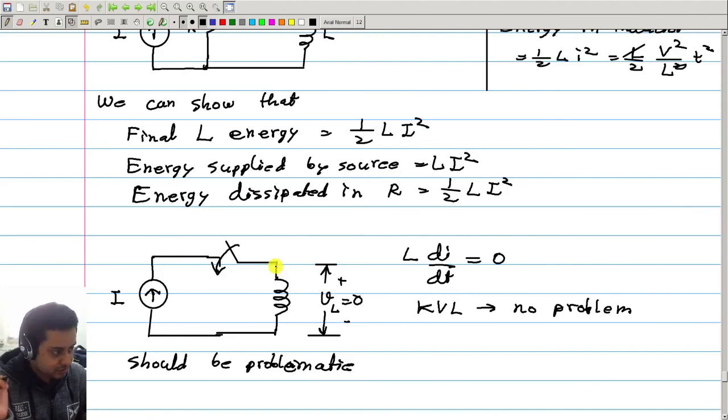If we are considering the current I to be a step function, in that case the voltage across this inductor will simply be a spike, right? That will actually be a delta function. So how can we then calculate the power dissipated, or the power supplied by the source? We are basically multiplying a delta function by a step function. How do you do that? That is also difficult, because delta multiplied with a constant.